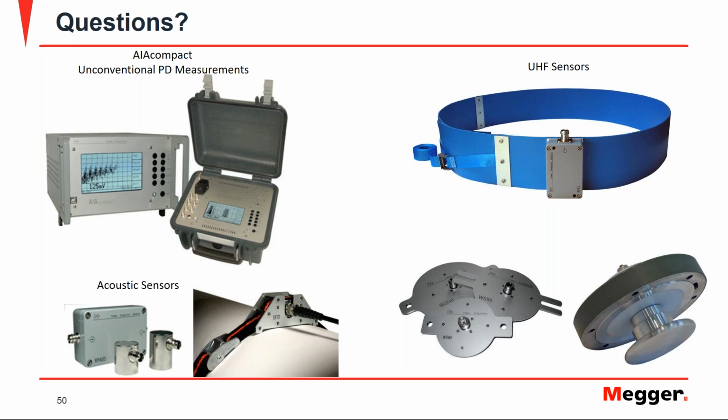An alternative solution would be to utilize the gating functionality that is available with most instruments. For gating, I pick up the noise signal with an external sensor. That can be a disturbance antenna that picks up airborne signals, or an HF CT that picks up noise that might be reaching our measurement through the grounding of our setup. And then I provide this noise signal to the gating input of my instrument, and it blinds out the noise signals from my measurement. So there are different options available, and it depends a bit on the type of noise that we are facing.